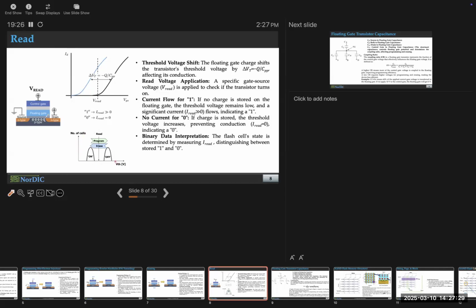I covered this concept many times. When I say that you have a threshold voltage for the transistor and you have a threshold voltage with charge trapped, there are two levels of threshold voltage. Do you all agree? I just need to put a reference in between. I will repeat myself again. There are just two levels of threshold voltages in the flash memory. One without the trap charge, the other with the trap charge, and I just have to put a reference. Is that right or wrong?